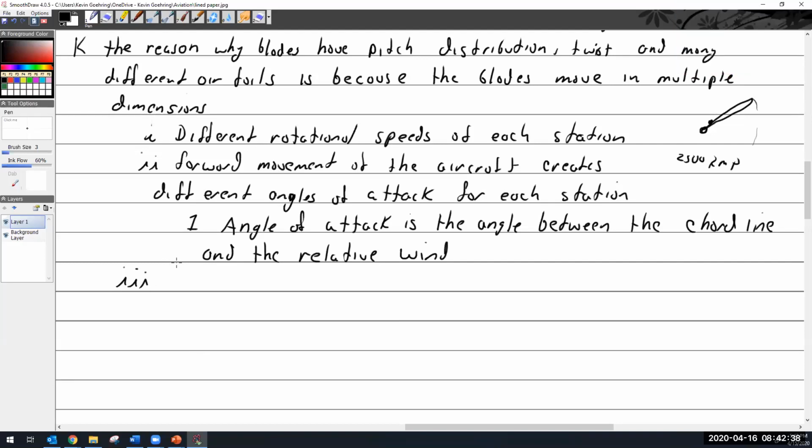Hey, Kevin, I have a question. Yeah. So you said on the type certificate data sheet, you would increase the pitch or the blade angle. Yep. In order for you to take a bigger bite out of the air, right, and therefore go faster, right? Yes. So does that mean more thrust? Yes. But see, now the actual question is, it's going to be spinning slower. So wouldn't that mean it's not producing as much thrust? You are a very astute guy, and I was almost hoping nobody would notice that, at this point.